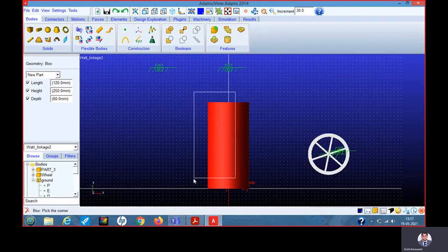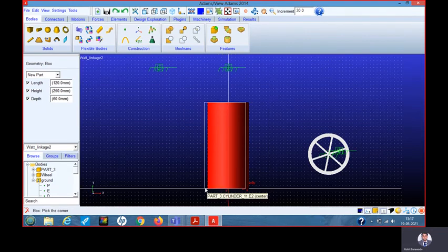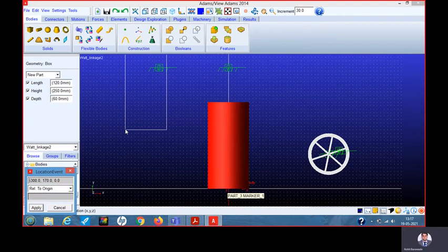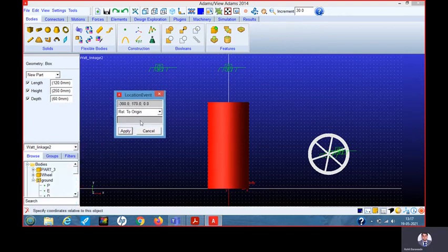It comes and we have to put it on this point, actually this center point, but it will not place accurately. So what we do, we give this particular point with the help of coordinates. You have to single right click. After right clicking, this location event opens. On this location event, you have to give the location where your box is placed. So our location is -60. Okay, so apply it.